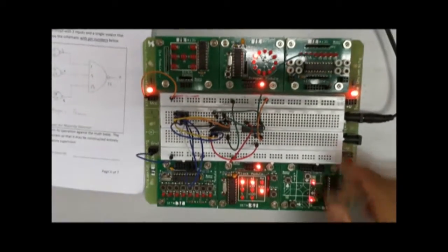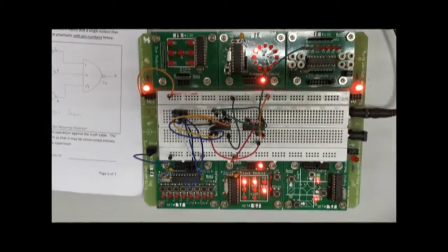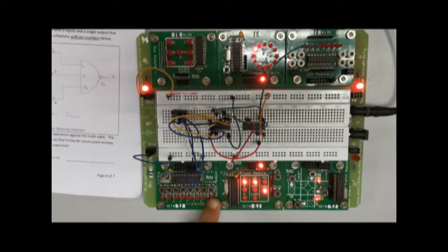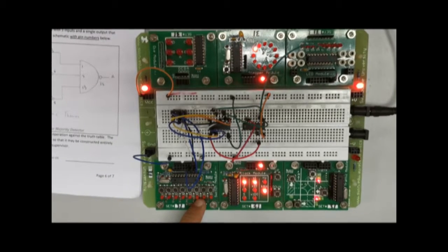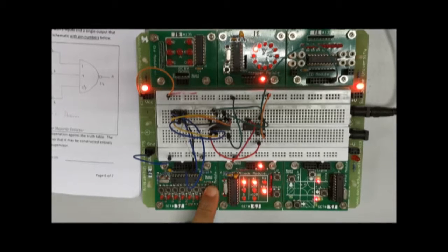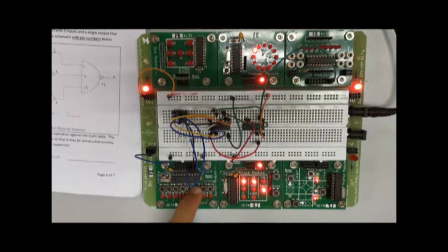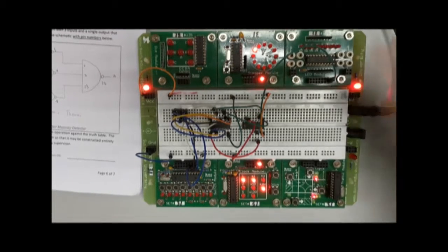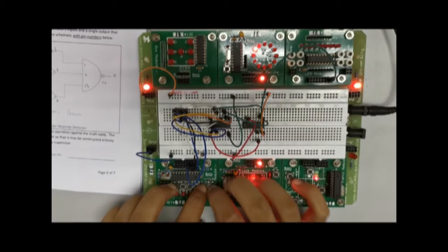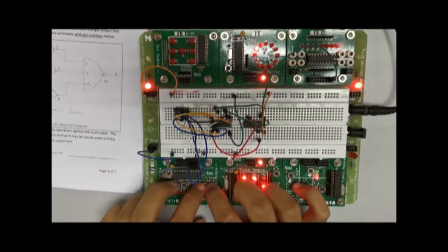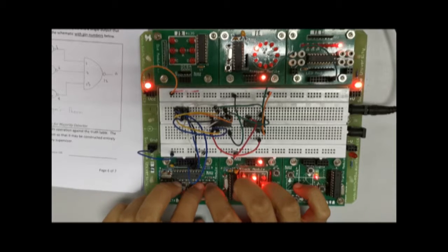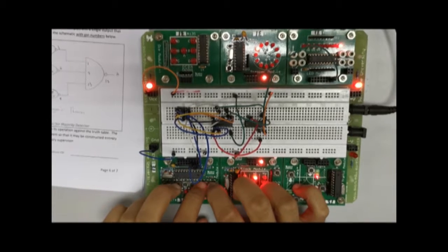If you look over here, this is our constructed circuit. This LED will light up when it returns a positive value, and these are the 3 switches that we have for inputs. So if you press a single one of them, it'll never return a positive value. However, if you were to press 2 of them at the same time, then it is to return a positive value, or all 3 at the same time as well.